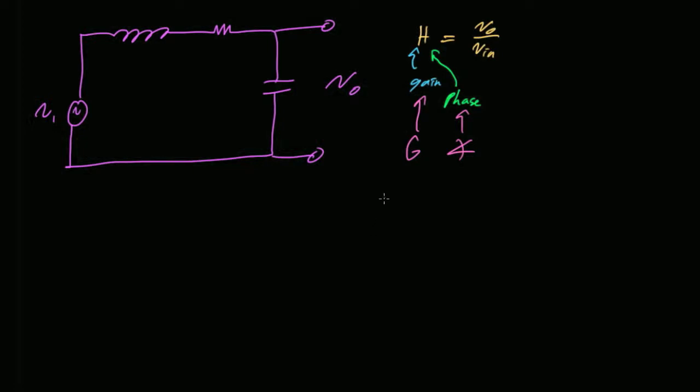Okay, so we're going to be looking at our input for this. V in equal to cosine of omega t. So just an input cosine signal, and our output is going to be equal to some gain times cosine of omega t plus phase shift. Okay, that's that phase component of the transfer function. So the transfer function contains information about V out and V in, magnitude, and phase.